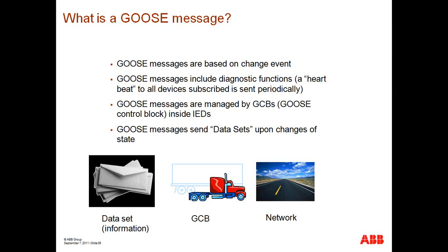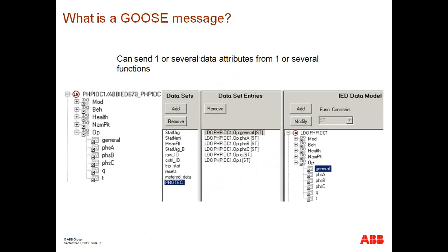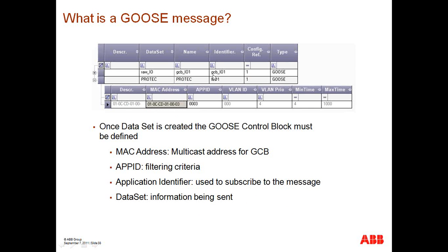In the case of GOOSE messages for protection-related applications, it is important to utilize what are called VLANs, or virtual LANs, and assign proper priorities to that traffic, in such a way that the switches used to form the Ethernet network will be smart enough to assign proper bandwidth to those communication messages that are time critical.